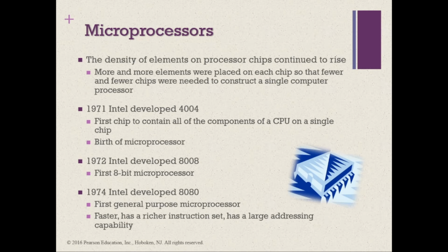There is no clear-cut measure of this, but perhaps the best measure is the data bus width, or the number of bits of data that can be brought into or sent out of the processor at a time. Another measure is the number of bits in the accumulator or in the set of general purpose registers. Often, these measures coincide, but not always.